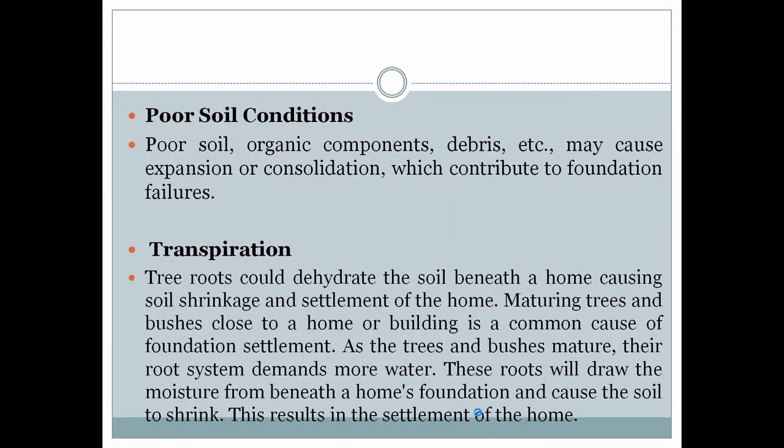Poor soil condition or transpiration. Tree roots could dehydrate the soil beneath a home, causing soil shrinking and settlement of the home. Maturing trees and bushes close to a home or building is a common cause of foundation settlement.